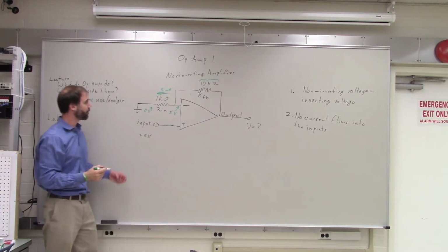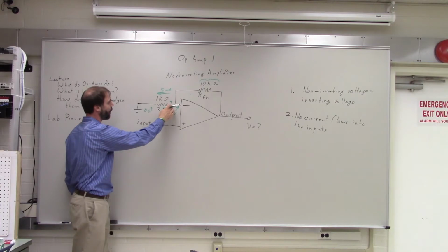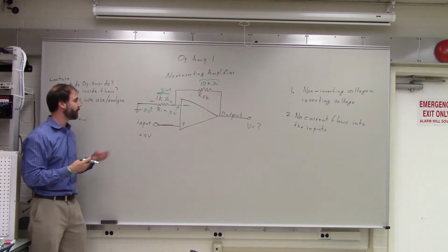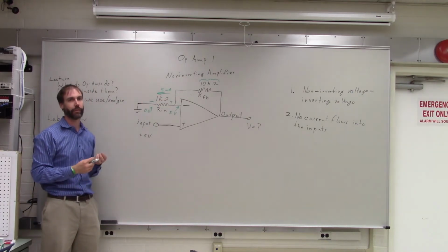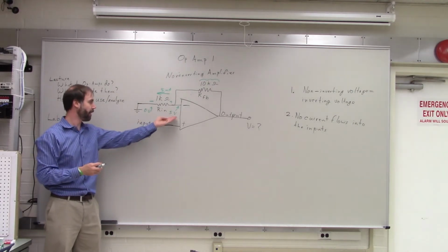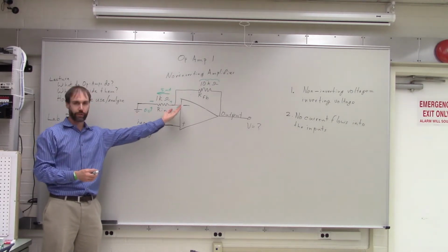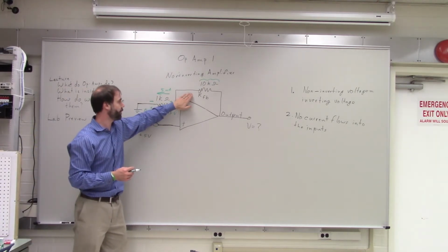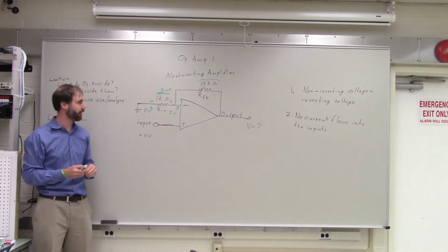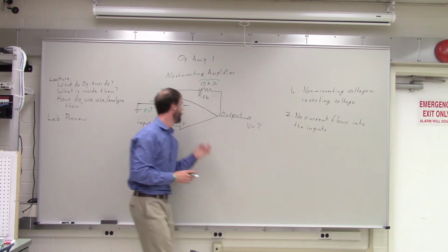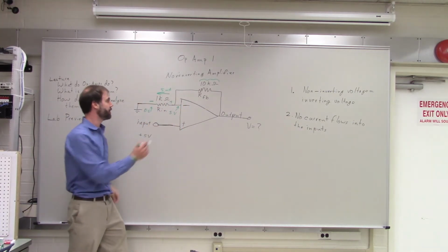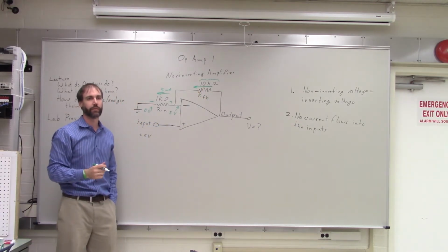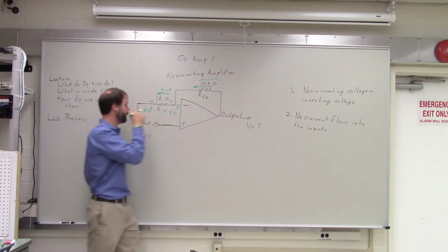Now, this time the voltage is more positive on the right-hand side of the resistor, and it's lower on the left-hand side. So that means the current is going to be flowing from right to left here. Okay? How much current is flowing into the chip? None, exactly. That's what Rule 2 tells us. So we have no current flowing into or out of the chip. So that means how much current is flowing through this resistor up there? 5 milliamps, exactly.